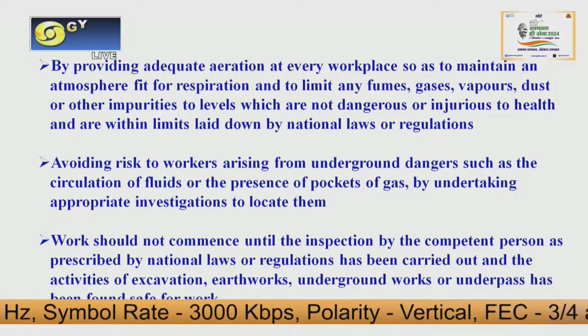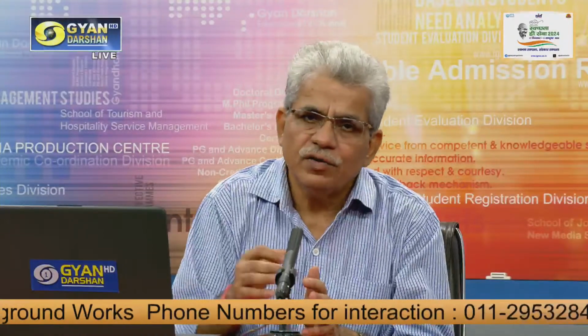Before beginning the work, before sending our workers there, proper inspection and survey should be done to check whether there are any pockets of gases or fluid. If we inspect that area before starting our tunneling or underground work, we can avoid any such accident.